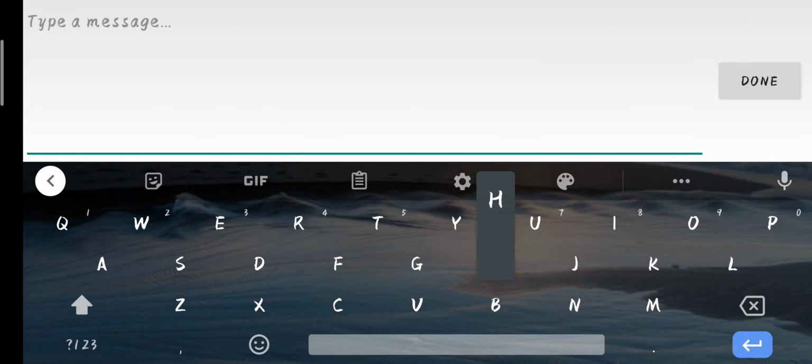Because the nature of the circuit is underdamped, the current will reach the maximum and fall back to 0 at point A. Then this is a point where both the thyristors T1 and T2 are off, between A and B. So when you trigger the main thyristor with gate current IG1, the output current will reach the maximum point and fall back to 0 at point A. So from 0 to A, the current reaches the maximum and falls back to 0 at A.